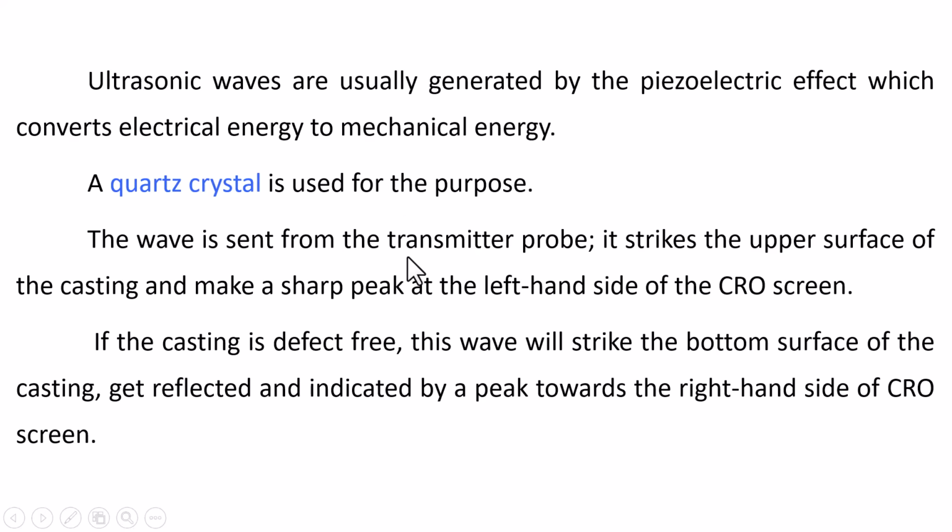The wave is sent from the transmitter probe. For providing this sound wave, we are using a transmitter probe, which consists of this quartz crystal piezoelectric material. The waves strike the upper surface of the casting and make a sharp peak at the left-hand side of the CRO screen. When it strikes the top surface, the small vibration shows a sharp peak on the CRO, the cathode ray oscilloscope screen.